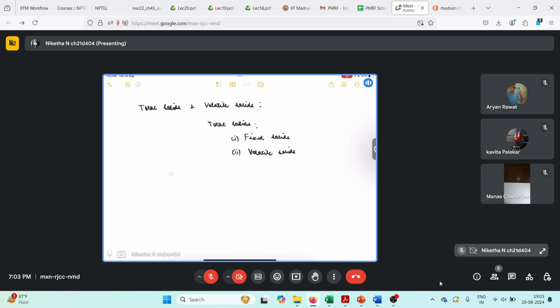So in order to determine the total solids, we will take a filter paper and we will pass the water through the filter paper, and the filter paper will be dried at 105 degrees Celsius. Sorry, not the filter paper, the entire sample itself will be dried. We use the filter paper to determine suspended solids, but since we are talking about total solids here, we don't need to separate it into filtered or into suspended or dissolved. We can just directly take the sample of water and we can dry it out at 105 degrees Celsius.